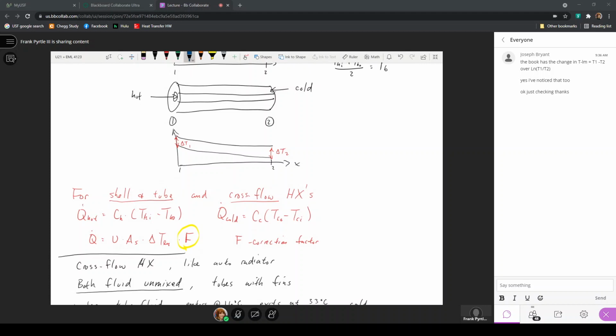So when we get into heat exchanger analysis, because of the complexity of two fluids moving at different velocities with different configurations for the flow paths, this expression of that overall heat transfer coefficient will vary according to any variations that you make to the heat exchanger, whether that be the fluid type, the fluid velocities, and of course the geometry of that particular heat exchanger.